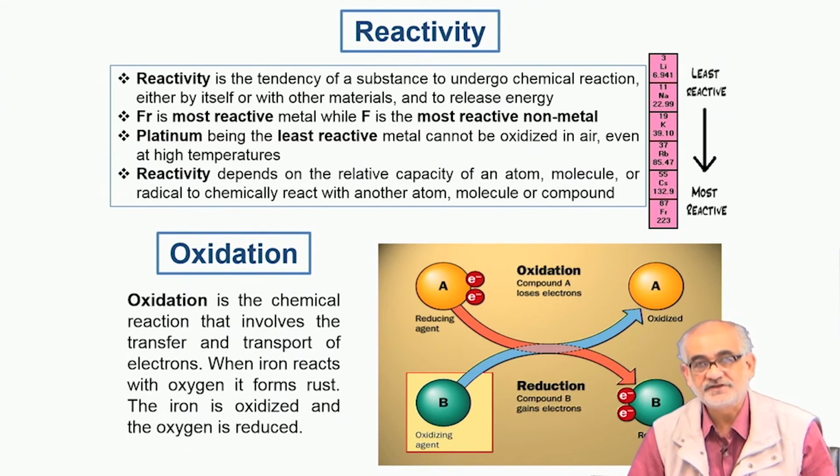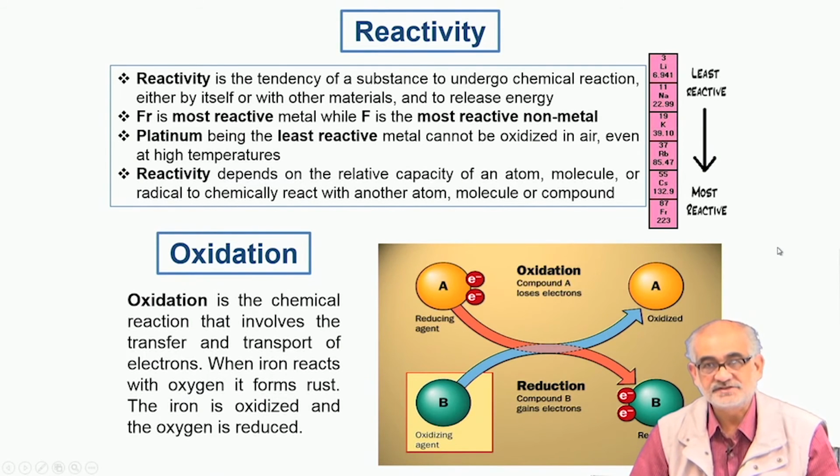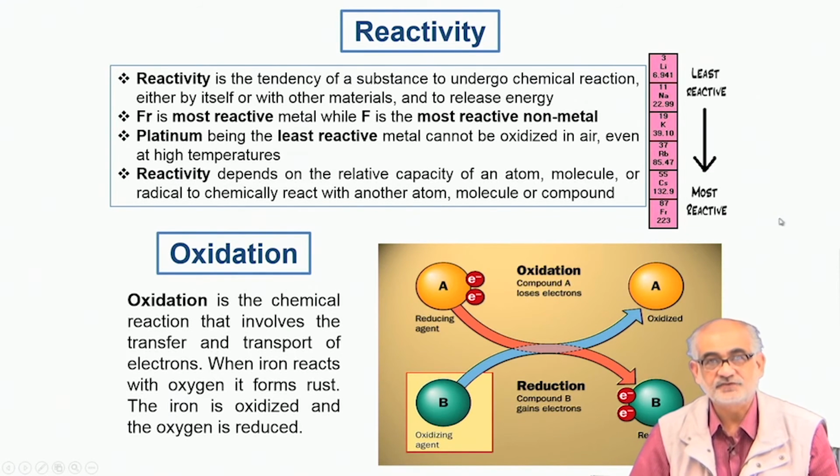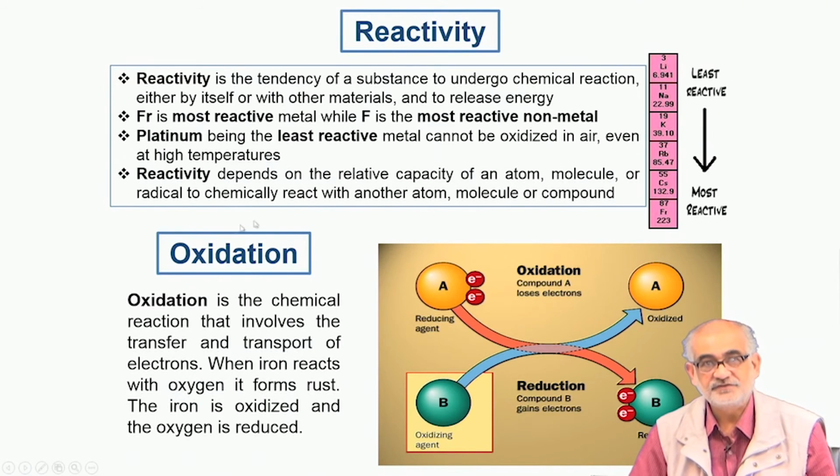So from the atmosphere, we pick up certain anions, maybe oxygen, maybe chlorine, and if we have a metal or other solids ready to offer certain cations, these anions and cations are likely to react immediately depending on their tendency of reaction, and the rate or degree of such reaction would be much higher at higher temperature, which is what happens in case of oxidation. This leads to gradual conversion of the solid into a different form, which is mostly undesirable, and we need to prevent it.